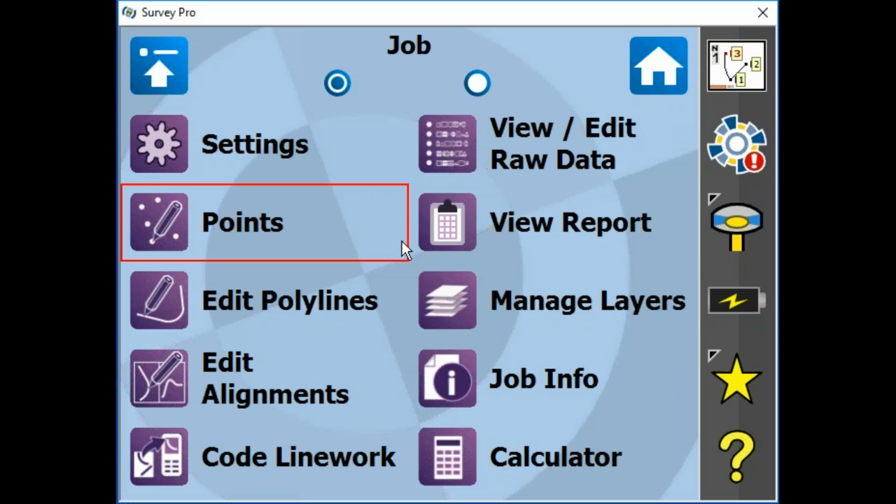It is important to understand what physical effects you're correcting for, and how that automatic ground mode versus being in, again, the default behavior is when you pick a mapping plane, you're in grid mode and we apply grid scaling, which Survey Pro is calculating for you based on each setup, right? You really do want to understand what you're doing if you apply a ground scale to that mapping plane mode. I definitely like to show that routine off because I'm pretty proud of it.